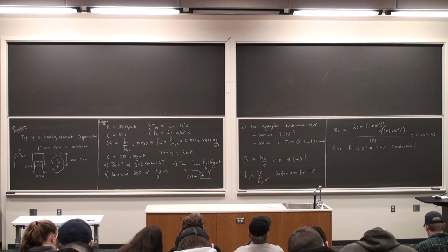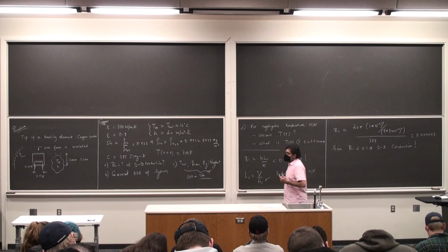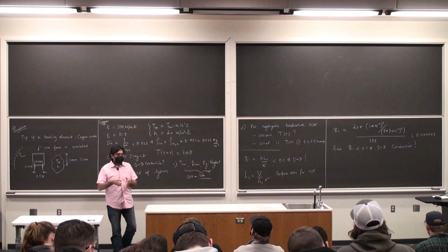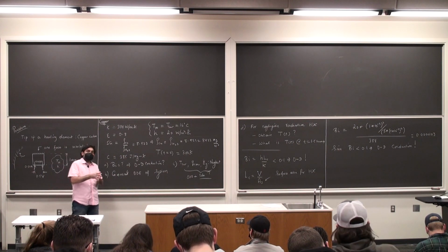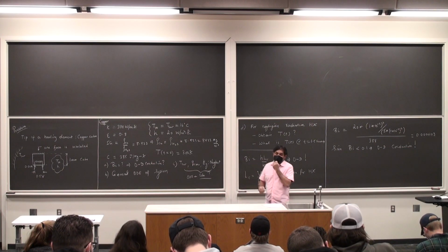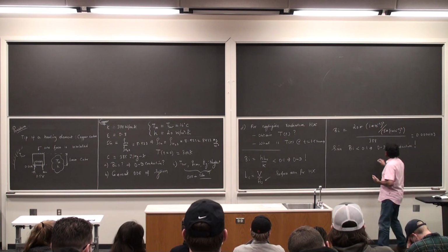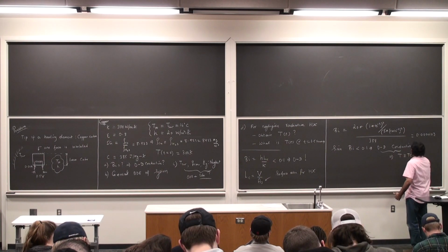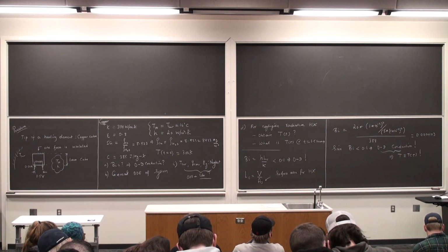Even though we solved partially the one-dimensional unsteady conduction problem, we will not be solving any problems on that. That was just meant as a way to mathematically show that if I have a Biot number of less than 0.1, which comes from the 1D unsteady conduction, then I can assume zero-dimensional conduction. Zero-dimensional conduction implies that temperature is a function of time only. Okay? And so that's the first part of the problem.